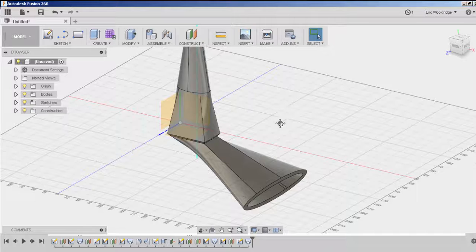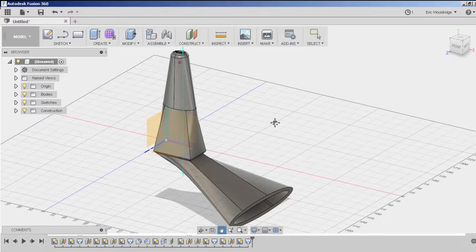What I highly suggest you do that's another feature of the loft. What I suggest you do at this point in time is play around with it, create some shapes, make sure that you go back into your sketches after you've done a successful loft, and then stretch and change the shapes of your cross sections so you can kind of see the differences and see what you can make this way.